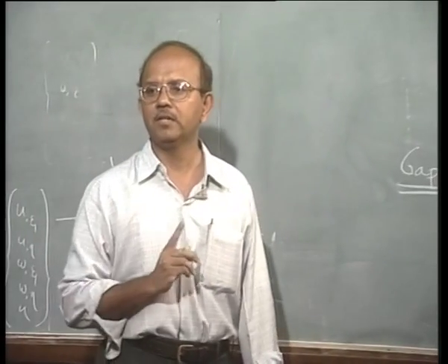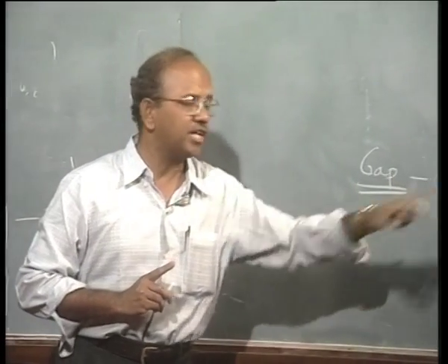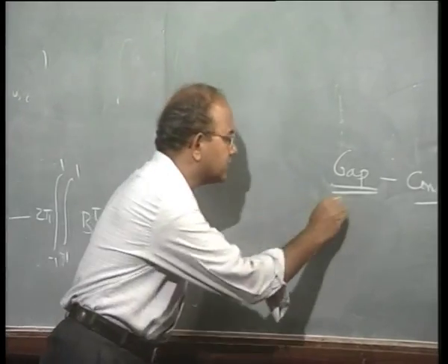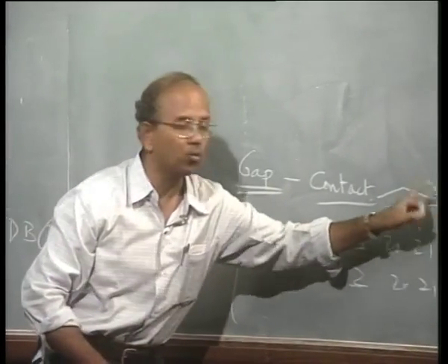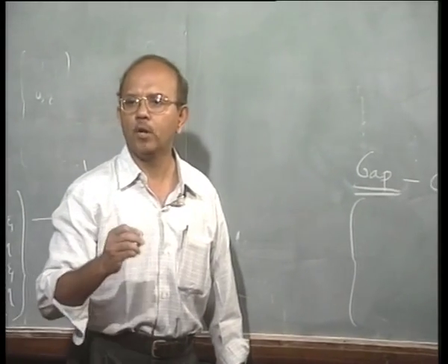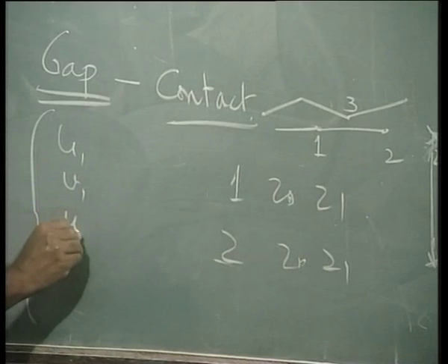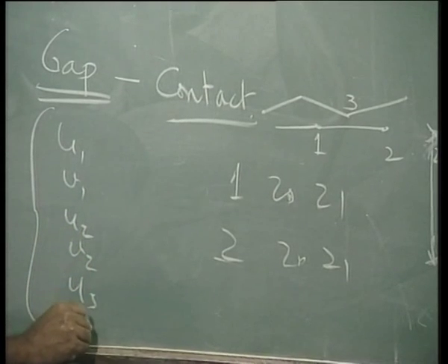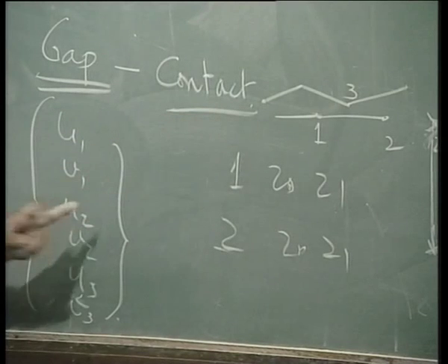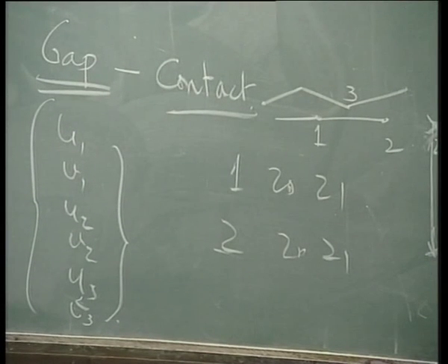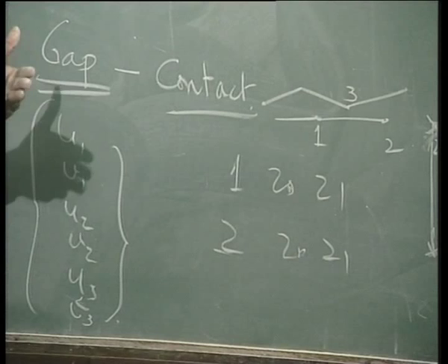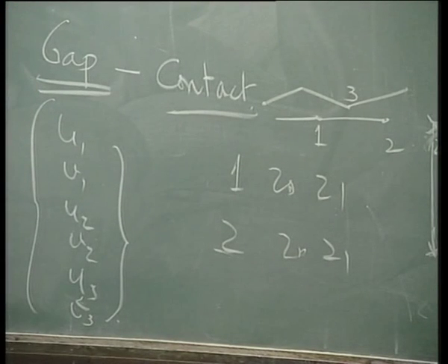The D's, what are D's? Understand that they are the degrees of freedom. The degrees of freedom that are associated with a slave node are 6 in number, say suppose I say 1, 2 and 3, then u1 v1, u2 v2 and u3 v3, and hence the K matrix is now correspondingly 6 by 6, and hence there are correspondingly 6 forces also.